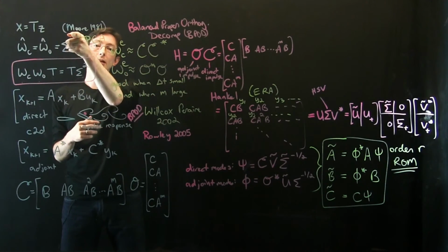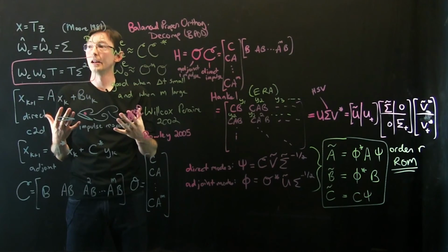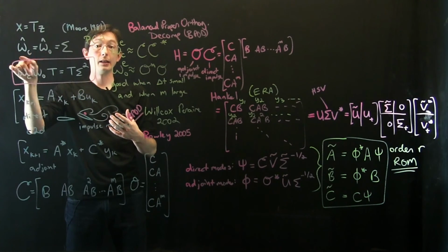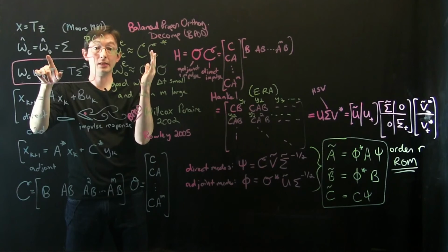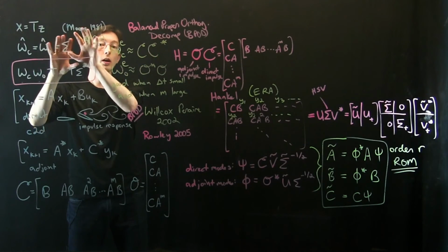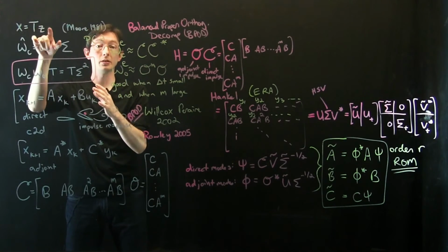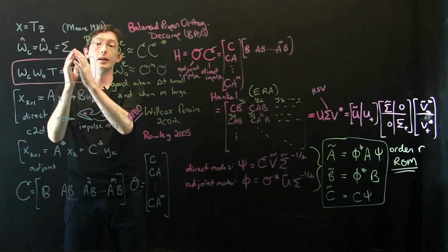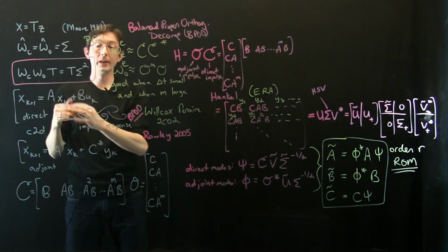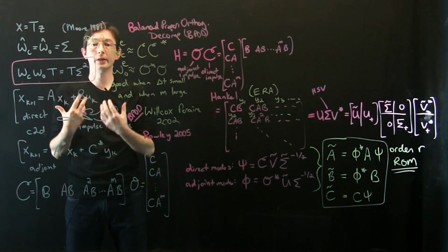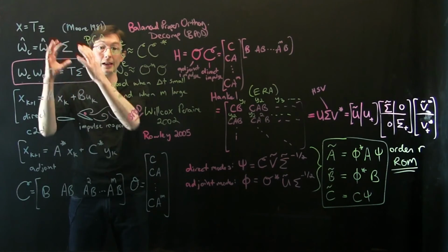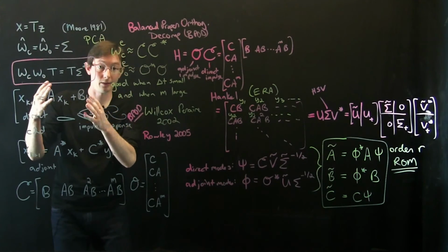What Moore said was there are degrees of controllability given by the directions of the Gramians. So Moore allowed us to hierarchically arrange our state space in a new coordinate system so that we could get a reduced order model in terms of the most controllable and observable directions. That gives us a reduced order model that we could do control with.